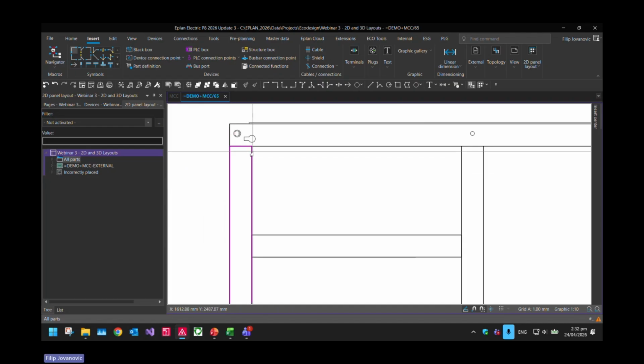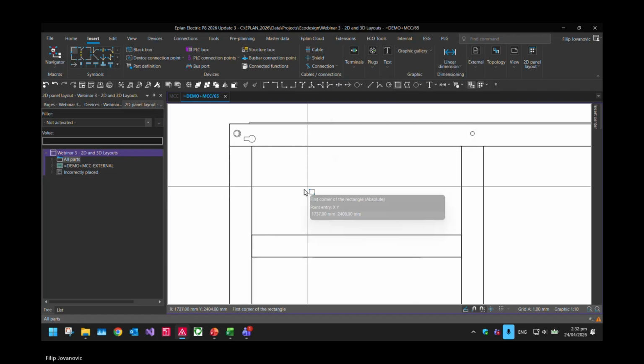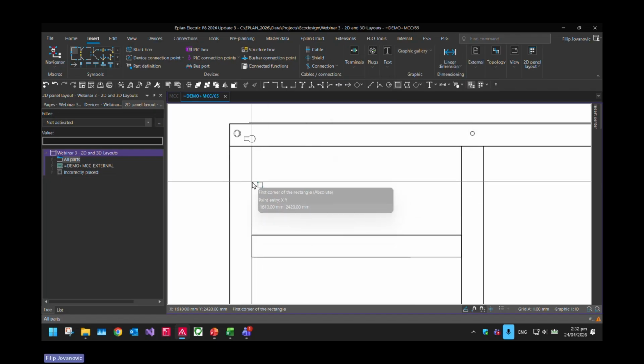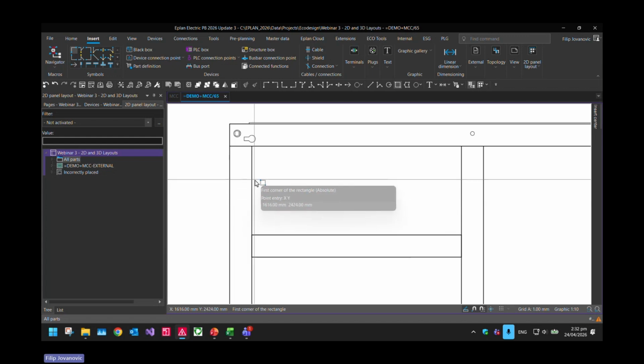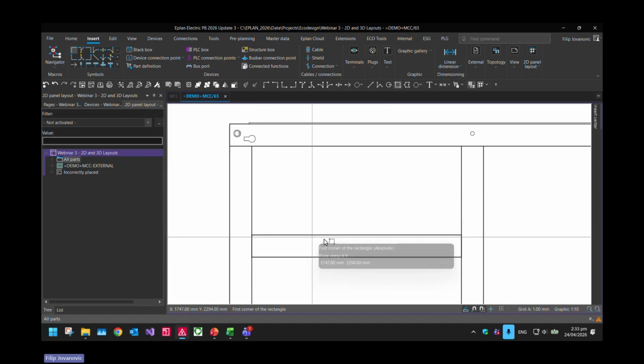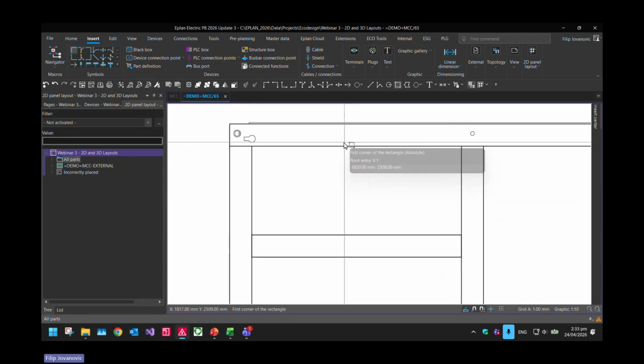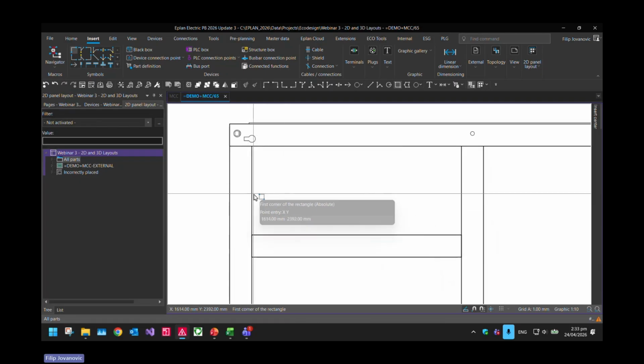Now I want to place a DIN rail in here. So again, do the rectangle. And I'm looking for that middle point, to the red square. And unfortunately, there's no snapping point for me. So as a quick tangent, the way this snapping works is you can snap corners, you can snap the middle of an object, or intersection, or anywhere where it intersects. Since I don't have a middle point here, I'm going to make my own.